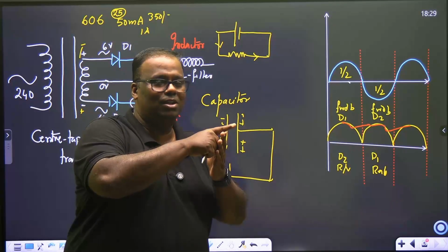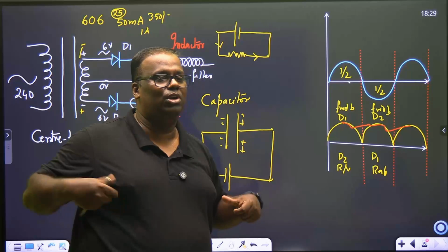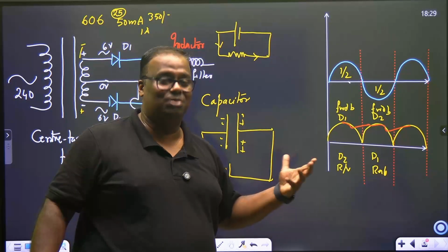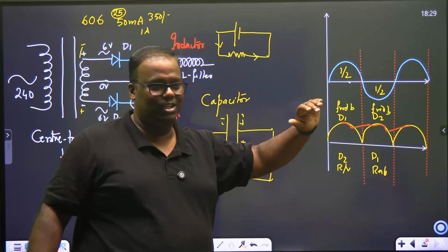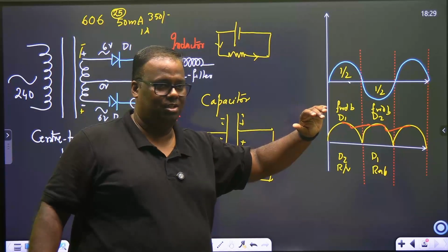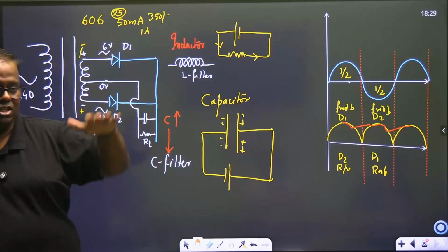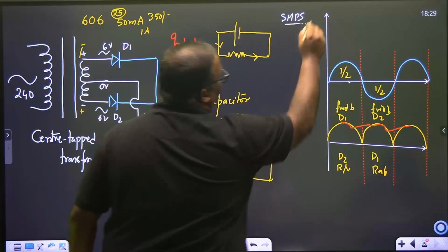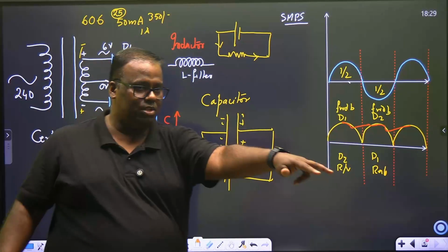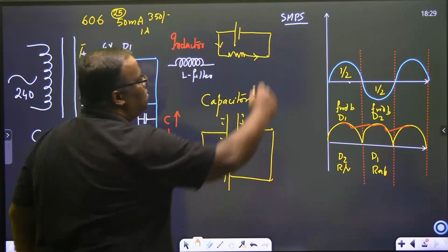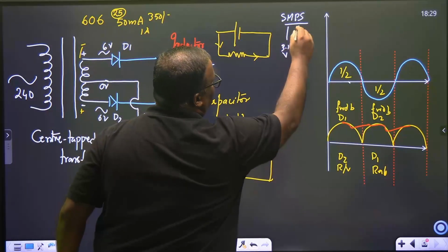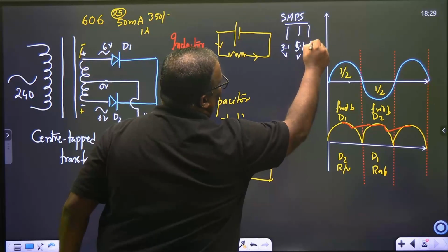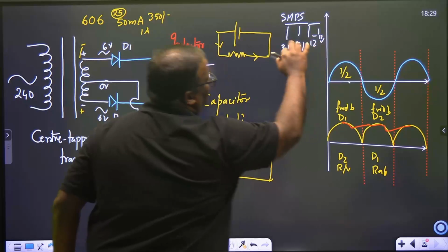You are seeing the mobile glowing up, but your mobile is actually fighting with the quality of input it is getting. Why do Apple and other devices cost so much? Because the type of filtration that they are giving is top notch. Even in desktops, we have got a device inside which we call SMPS, switch mode power supply. The 220 volt which feeds the desktop, this SMPS will give me 3.1 volt DC, 5.1 volt DC, 12 volt DC, and negative 12 volt DC.